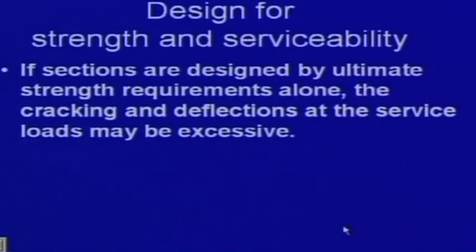Now, if sections are designed by ultimate strength requirements alone, if we simply consider the strength requirement with the ultimate load, then the cracking and deflections at the service loads may be excessive. This is another conflict, you can say.